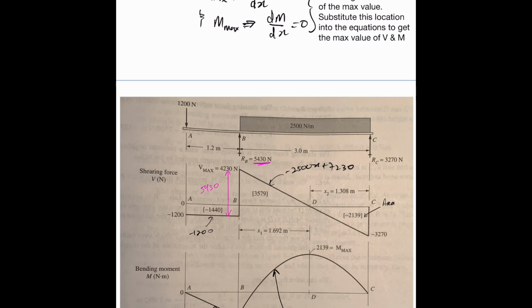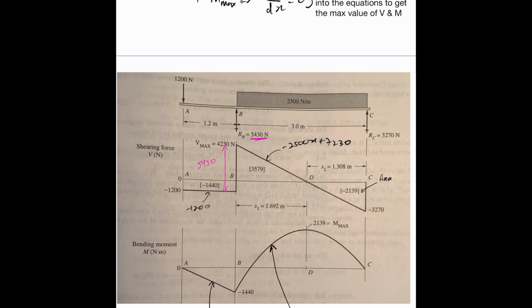If you look at the bending moment diagram, when they plot the graph, minus 12 with x minus 12 means negative, so it will go down, and then you do the parabolic plot. If you look at this quickly, you can see that this region has negative bending moment. So this is hogging.